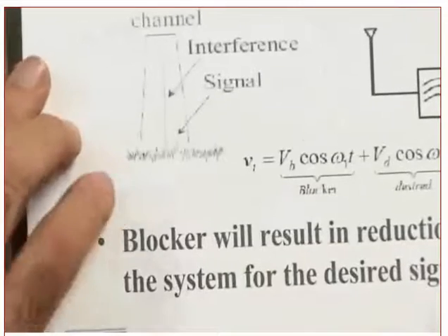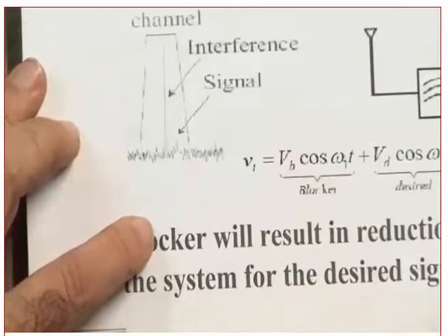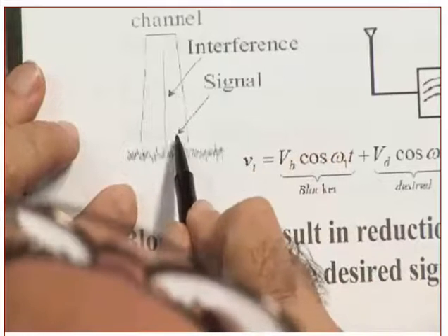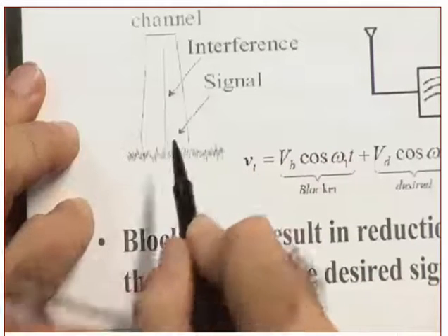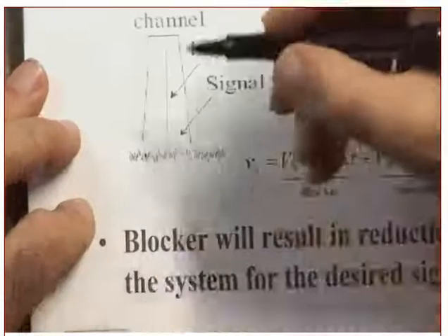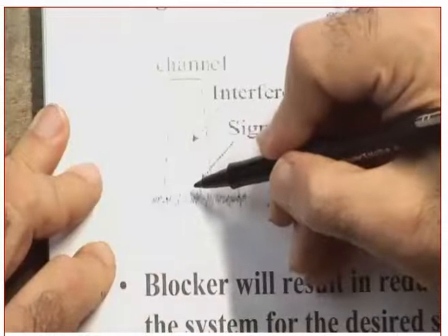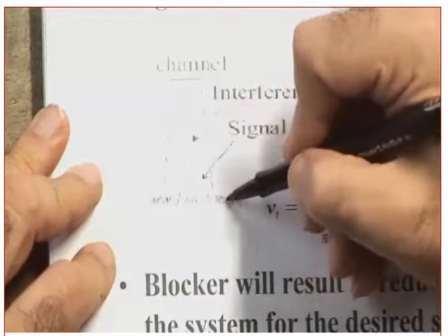Hey, very good zooming. This is not only very good zooming, but it is fast zooming. You see this peak? By the way, what is this? This is background noise. But do you see a peak here? That peak is the desired signal. What in the world is this? That is an interferer that happens to be close by. Yes? It is much stronger than the signal.